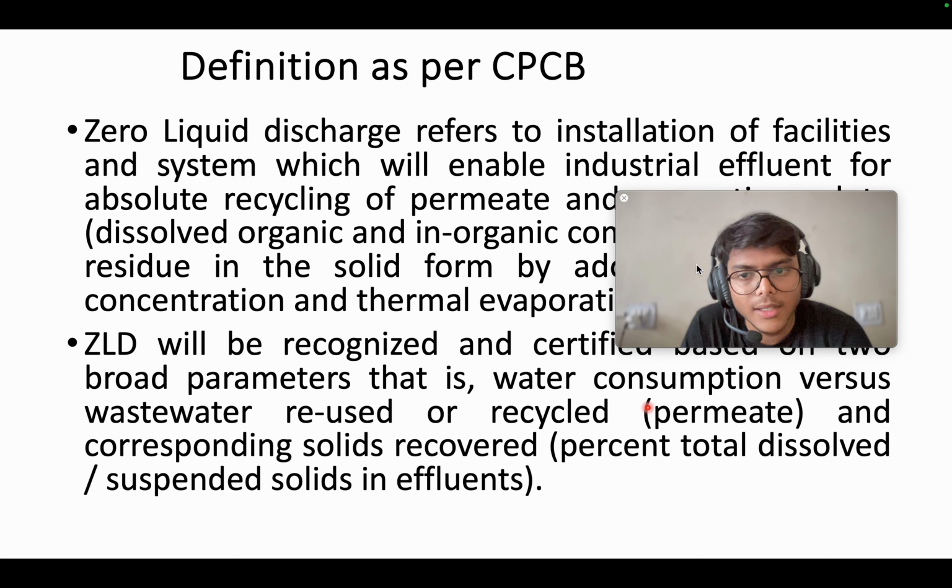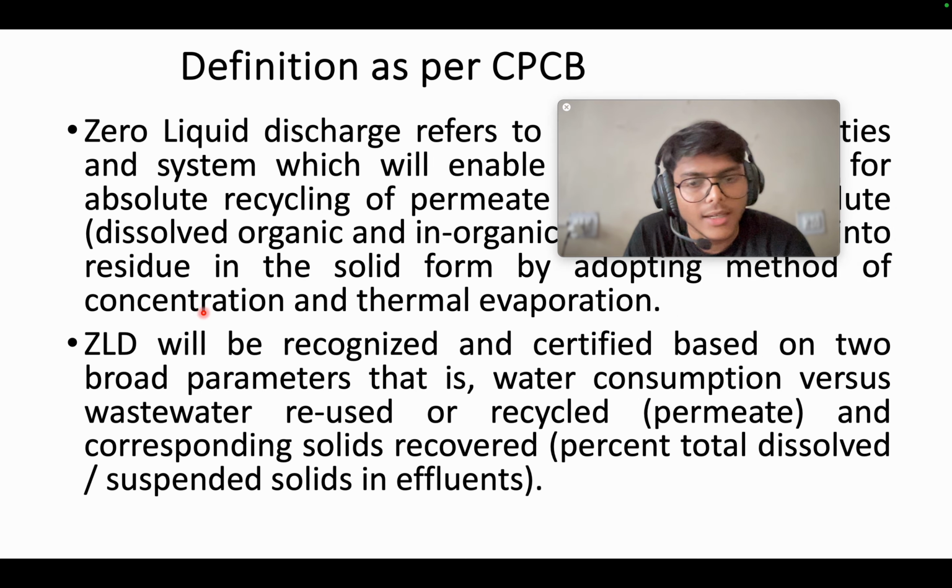Now, where can we recognize this ZLD method, right? ZLD will be recognized and certified based on two broad parameters, that is water consumption versus wastewater reused or recycled, and the corresponding solids recovered, that is, we have a formula called percent total dissolved or suspended solids in influent.